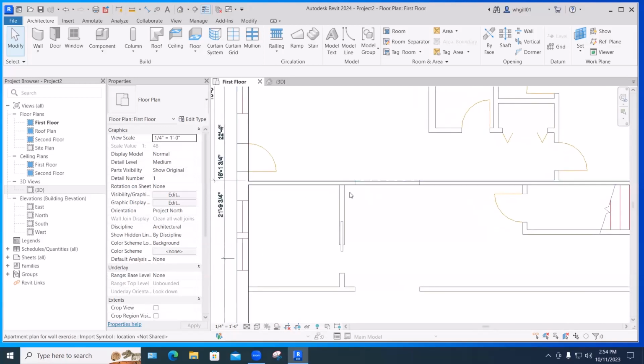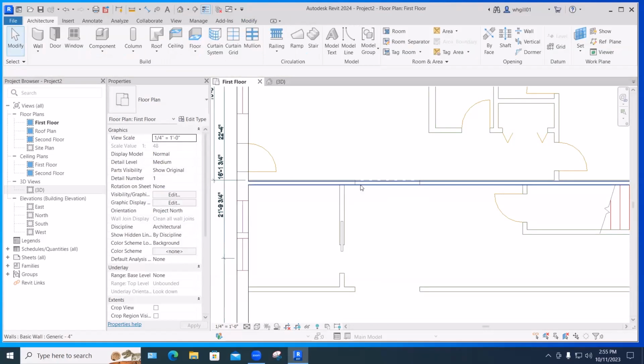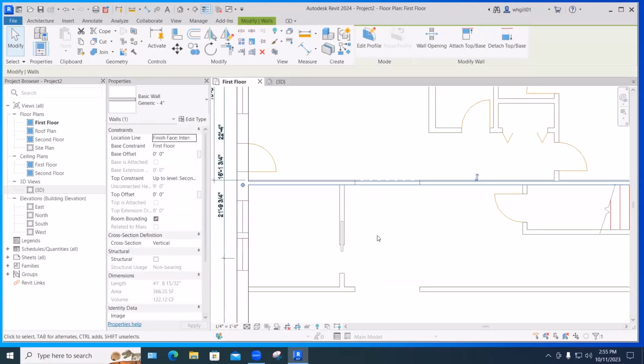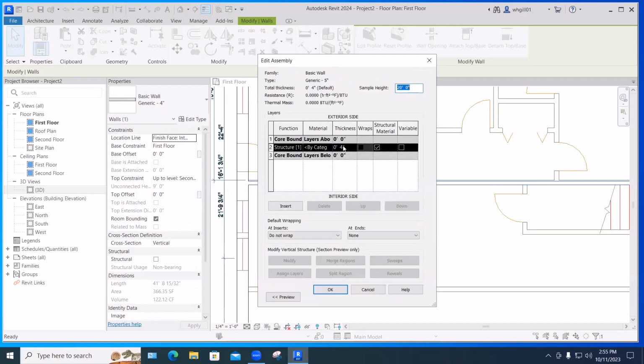And just as this wall was too skinny, the 8-inch or whatever we used here needed to get fatter to become 12, this one needs to get fatter to become 5 inches. I pretty much leave it set on interior just as a way of working. Once I have this, how do I change a 4-inch into a 5-inch? Edit Type, Duplicate. I guess you're getting sort of the idea of how this all works. Change the name. Now we've got to change the structure. 5 inches. Okay.